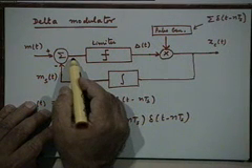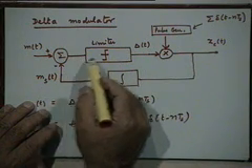So we are only capturing the fact of how many bits are being used to encode one voltage level. Only one bit is being used to encode one voltage level here. As you can see, all I am doing is taking the difference and encoding this difference into either a positive impulse or a negative impulse, single impulse, right? So in that sense it's a one bit quantization, single bit quantization. If you are looking at it in the A to D converter context, it is different. You don't use multiple bits for each sample. You use a single pulse, or actually a binary level, for representing each value of the difference signal.